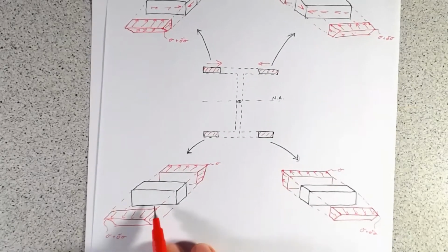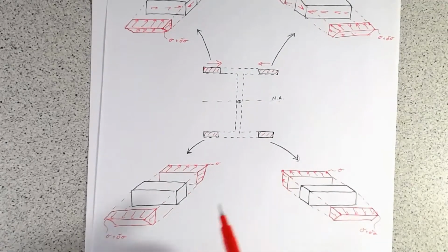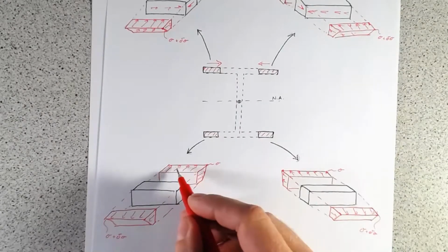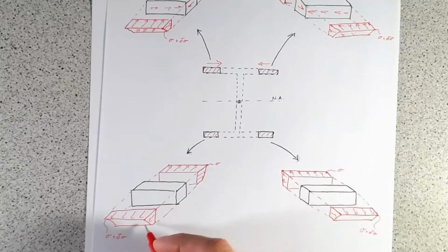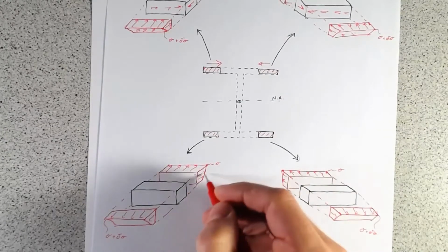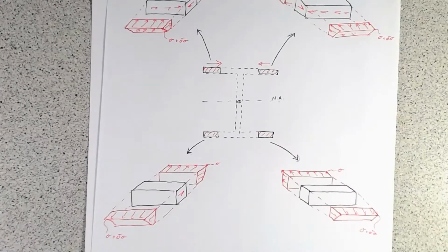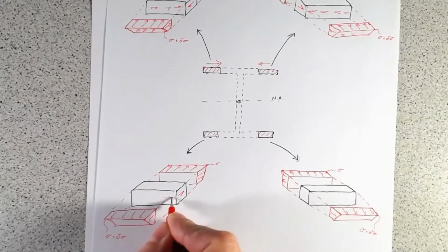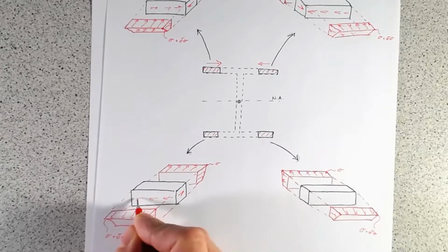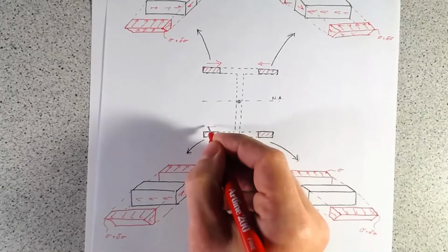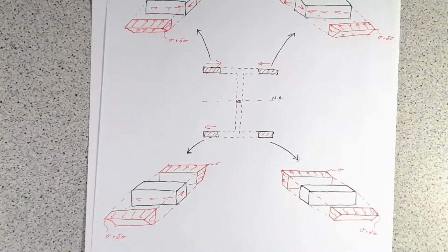So we've got our stresses pulling away. Again, d sigma is going to be on the face closest to us. So in order to balance it, we've got a bigger tension force here, so we need to give it a little bump going this direction. So it goes that way. And again, if tails have to touch tails at a corner and tips of arrows have to touch tips, that means our shear is going to go in this direction. So our shear is looking like that.